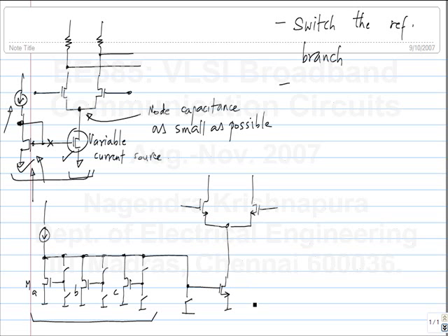That's correct. What happens if I don't have the switch? Yeah, actually this current source will pump into an almost open circuit and pull this node up to VDD. So then you get a large current. So we want to not have that case, so we should have a shorting switch to ground. So in practice, what we do is we turn off this current source also if we want to turn off everything.